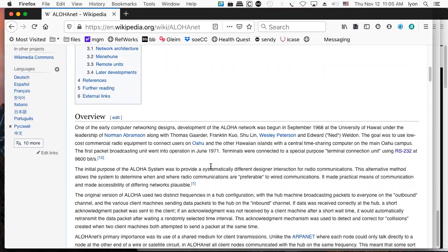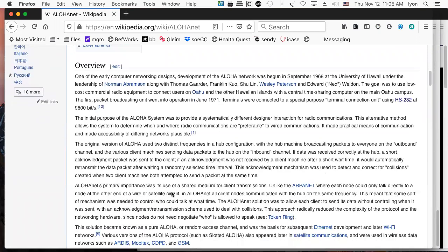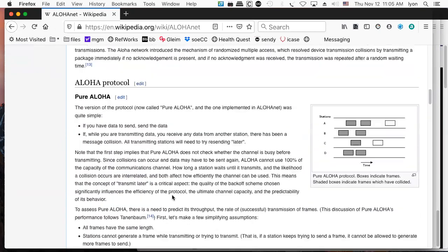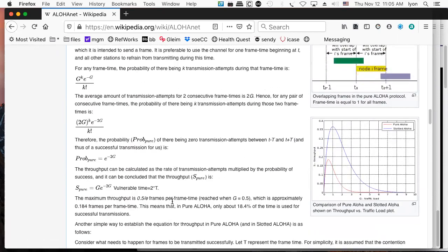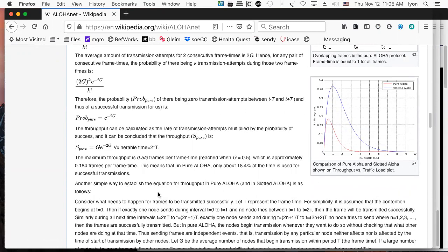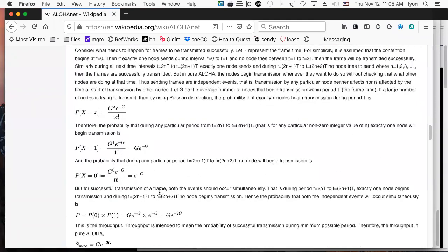And they effectively devised a means by which teletypes, they say using RS-232, but in fact it was using a serial current loop, could communicate. And so this is a system which is in use today by ham radio operators. I happen to be a ham radio operator with a packet radio modem. If you're trying to modulate so that you can basically use the voice band in order to be able to communicate digital data, you need some sort of a modem that's going to essentially be like a phone modem that works over the radio. And then you have to worry about a whole bunch of people sharing the same phone line, like a party line.